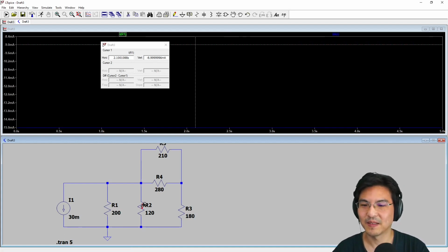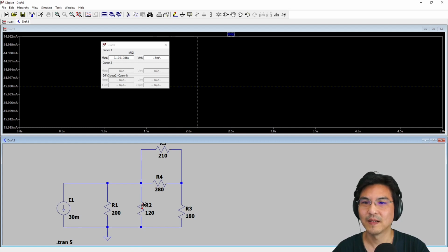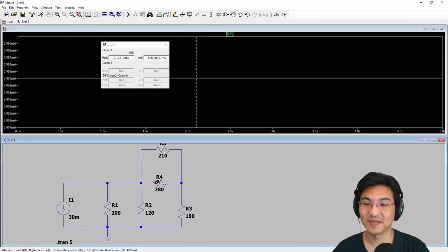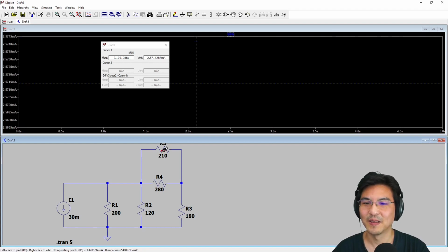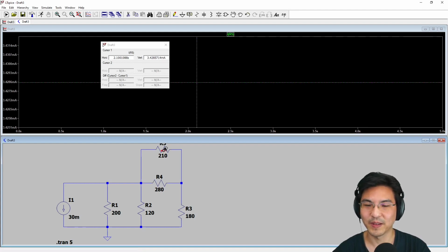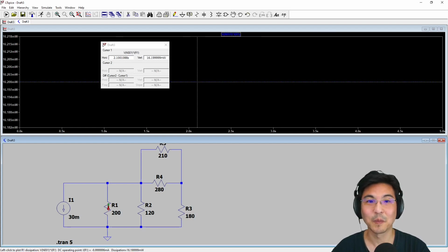And then the current here, minus 15, current here, minus 6 here. All right, so you can get the current through everything, and you can measure the voltage everywhere. And you can even do things like if I'm hovering over this resistor, if you press Alt, the icon changes to this kind of thermometer bulb, and that actually measures the power, which is just the voltage times the current.